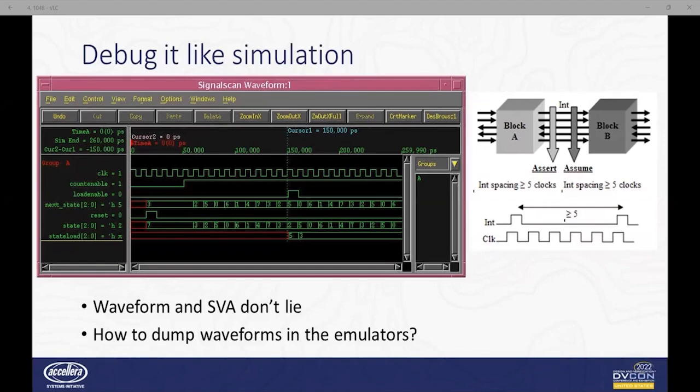We always compile the Protium build with some signal probes at key interfaces of the design. The probes should focus on the internal states of the device, which are not observable by software, such as the FIFO fill level, the back pressure tokens, timestamps of the packets, etc. The waveform capture is triggered on interrupts or error conditions. With luck, those signals will give us good insights into what's wrong with the RTL.